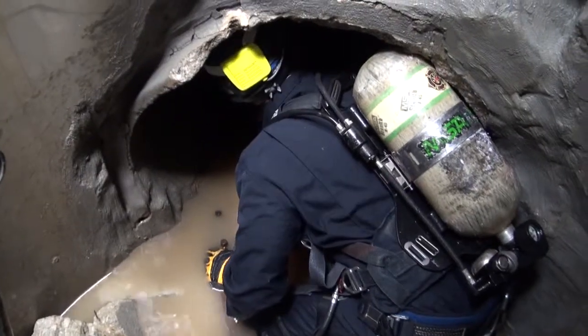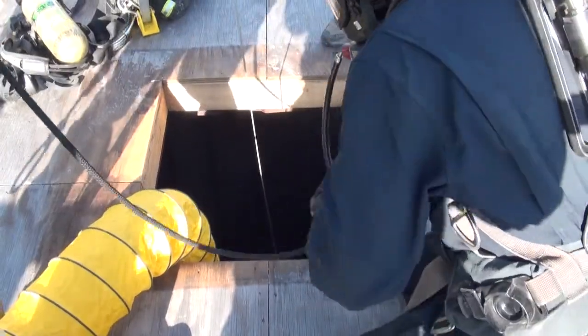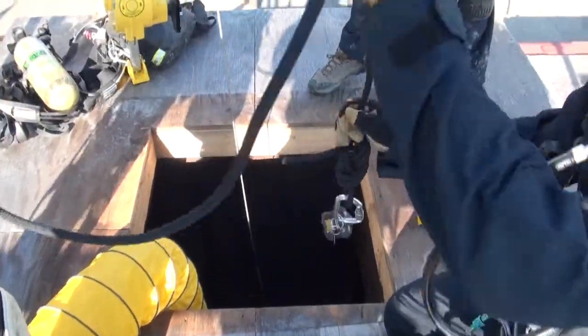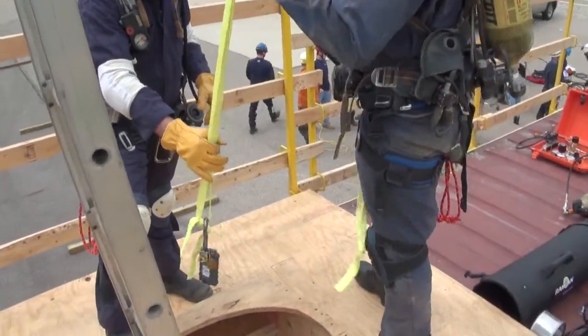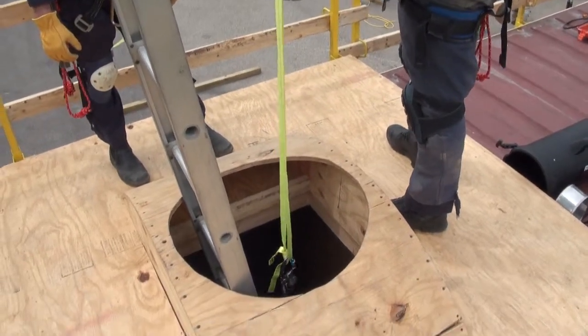As we continue to close in on the space, we want to focus initially on a recon perspective. So we're going to utilize our monitors to sample the initial opening and whatever we can get to with our probe or by extending this directly into the space. Now, if we don't have a sampling probe to where we can administer the probe into depth or into distance, then what we're talking about is attaching the atmospheric monitor to a rope or to an extension pole, some type of long-handled tool, and advancing it into the space.